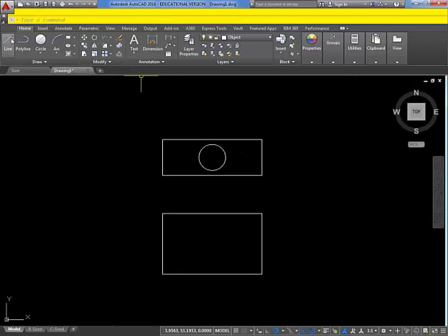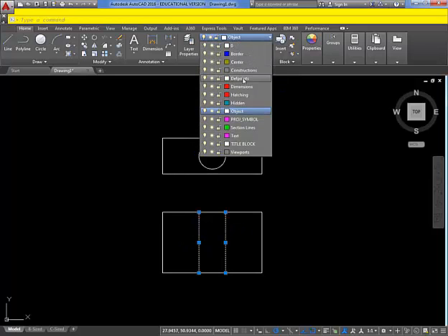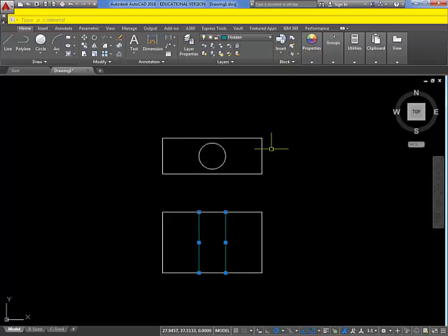And then I'm going to project that down to create my front view. Okay, and I'd have my center line in there too, but in the interest of time, I'll keep going. So if this was my front view, these would be hidden.